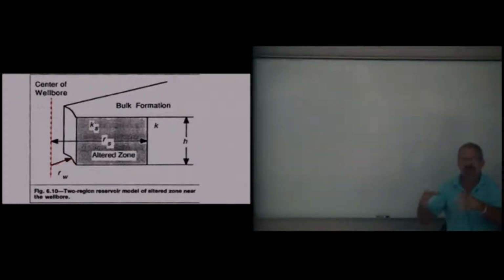If we're doing a real world problem, we find out the weight and grade of the casing, and it usually has a nominal diameter, which is approximately the outside diameter. Then the thickness, the weight and the grade will give us the ID. That's the radius that the reservoir sees the wellbore back pressure at.